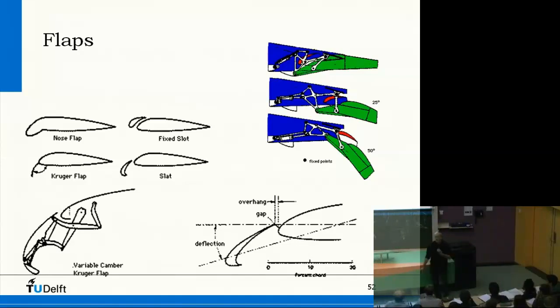If you extend the flaps, then you have very high velocities on the upper surface, but you fly at very low speed, right? So there's no critical Mach number involved there. If you would do that at cruise, then suddenly you would have very high drag, and then you would need a lot of fuel.